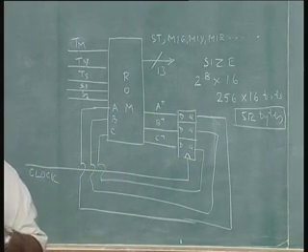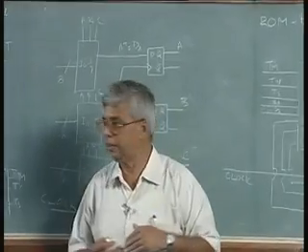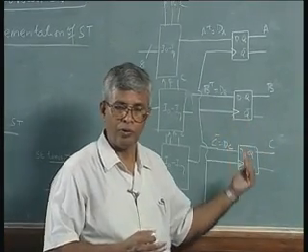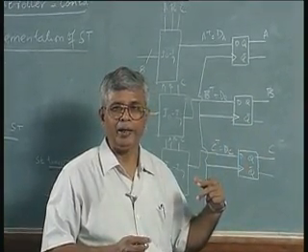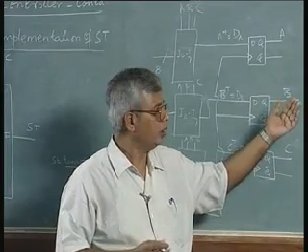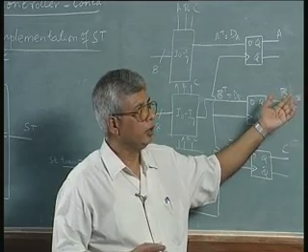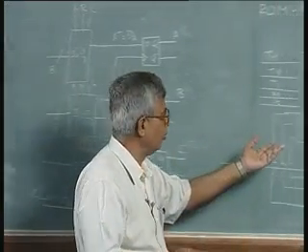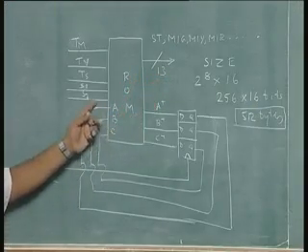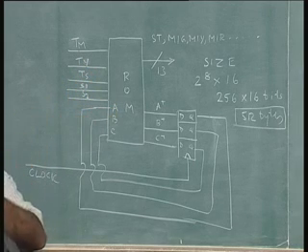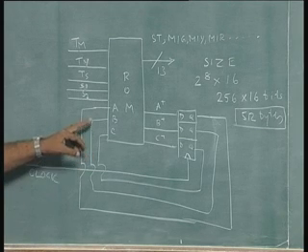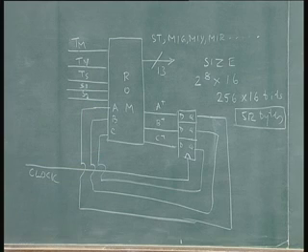It is very simple. My ASM chart will be expanded. In the ASM chart we had only rows corresponding to a condition. There are 8 states, 000 to 111. Each of these states, if you expand, will have rows for each condition. So, the size of the truth table would be 256, because there are 3 state bits and 5 condition inputs. We will have to write a row for each of these states and each of the conditions, which means my ROM truth table, ROM table as it is called, will have 256 rows.